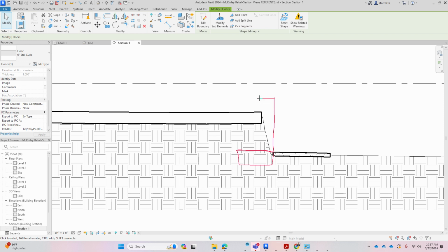The retaining rock wall is 1 foot wide this way, and I'm going to come here. And then from here, you actually draw it at a 45-degree angle. So this is what the retaining rock wall would look like. And of course, you trim all this stuff off. Here you draw in the little gravel to represent the rock wall. And then in here, you would hatch it with a little hatch pattern like concrete. So that's really what the retaining rock wall would look like.